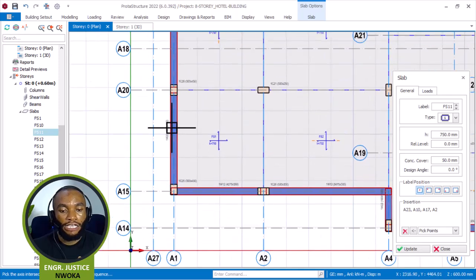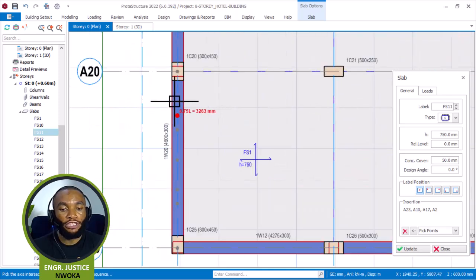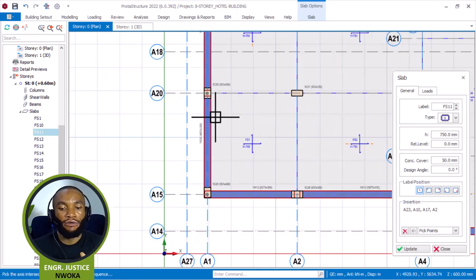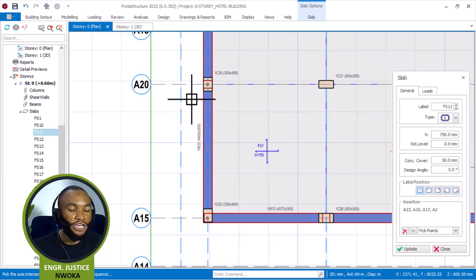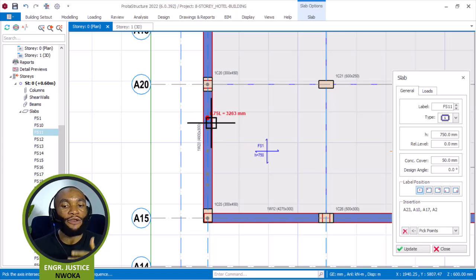This place now is going to have a slab to be able to spread the load that is coming from this wall, at least spread it a bit. Because right now, this wall is serving as a basement wall and also serving as a retaining wall. So right now we are meant to spread the load from this wall. Because right now there's a slab here, but there's no slab here. So without putting a slab here, there will be an overburden pressure